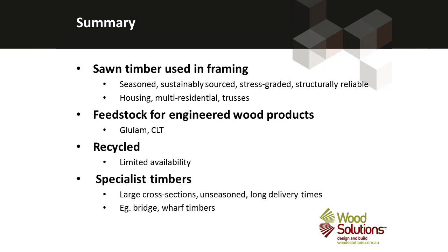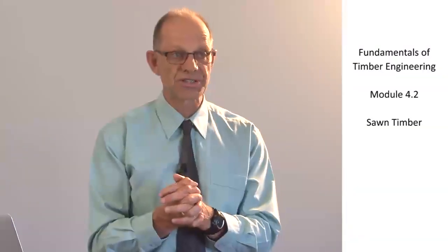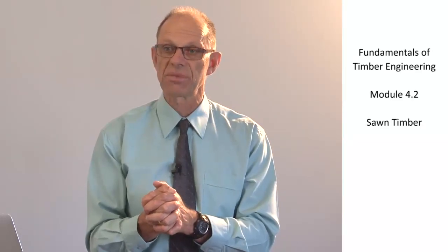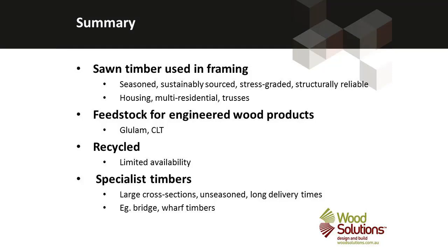So that sawn timber is often used in framing. It's used in a seasoned state, it's sustainably sourced, it's stress graded, it's structurally reliable. It's also used as a feedstock for some engineered wood products, and recycled timber is available in limited quantities, and if you're using recycled timber you need to check out the local availability first. Specialist timbers take a long time to actually deliver, but are required for some larger structures such as wharves and bridges.